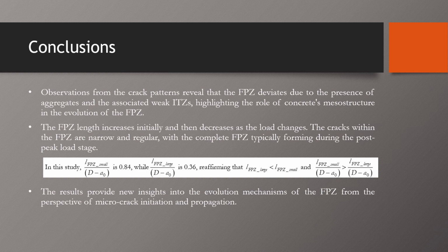One more important point is fracture process zone increases initially and then it decreases as the load changes. And the length of the fracture process zone in small size beams is more compared to the length of the fracture process zone in large size beams.